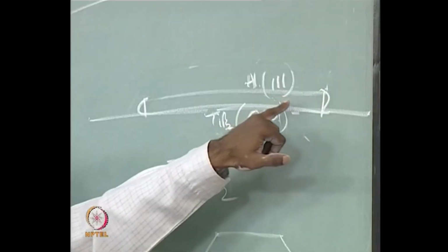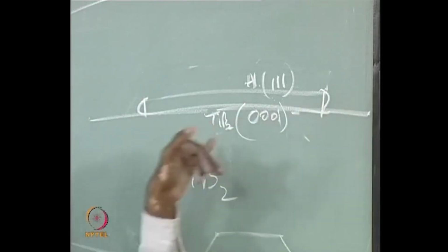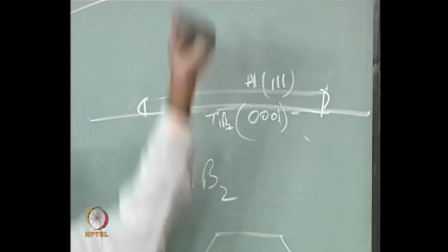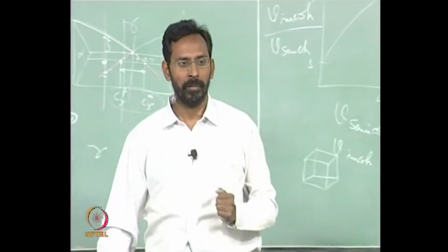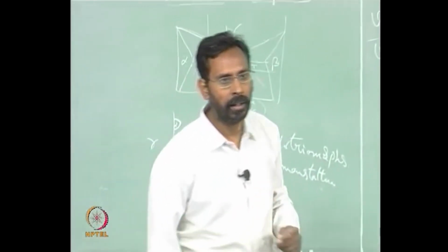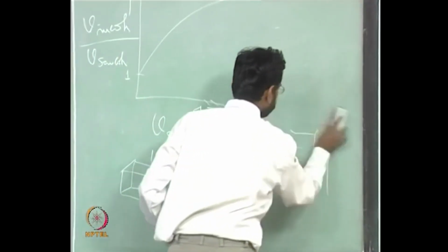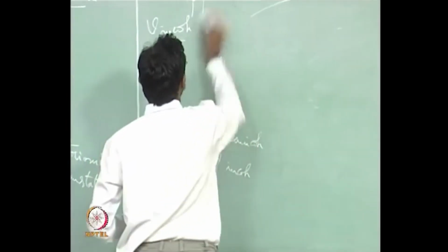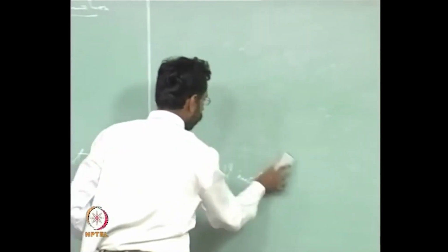Whereas if you look at low temperatures where such a nucleation has taken place, it is easier for it to grow in this direction rather than in that direction. If it has to go in that direction, continuously you need to maintain the coherency. Clear? Okay. So this is what you would see. So with that, more or less, we have understood eutectoid.